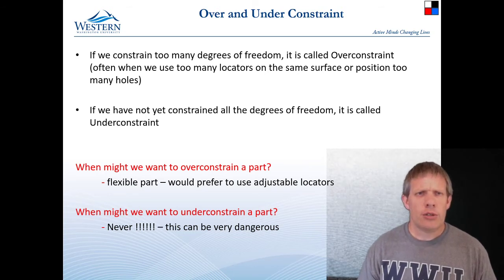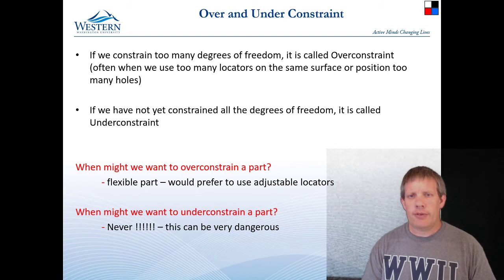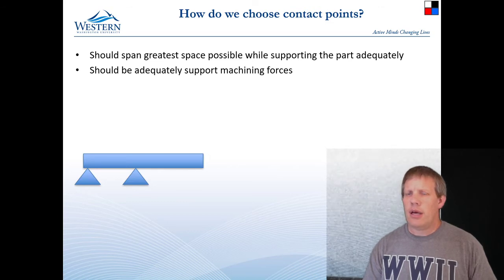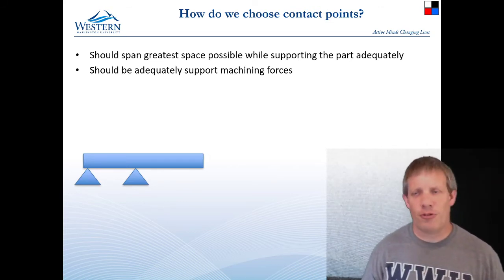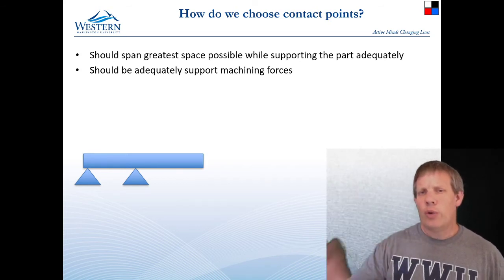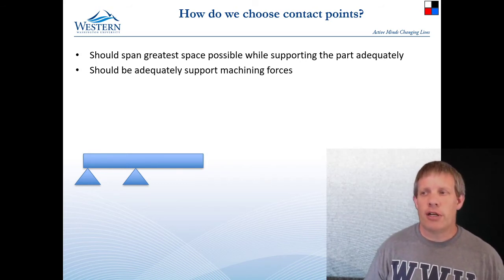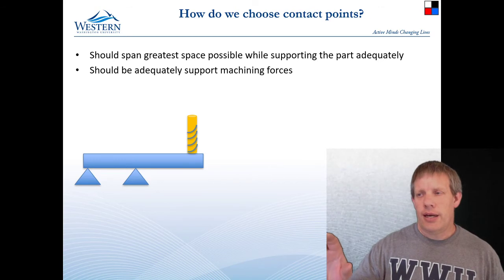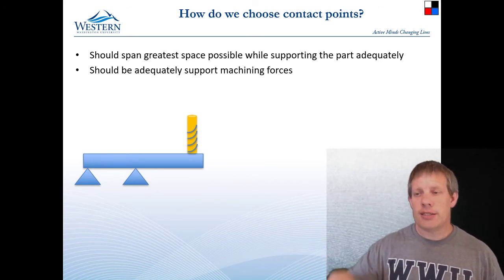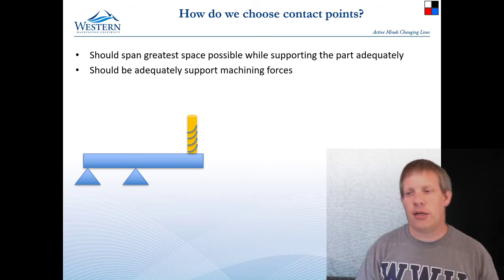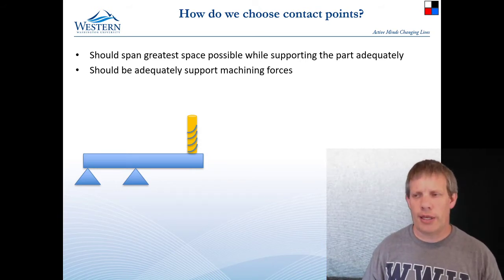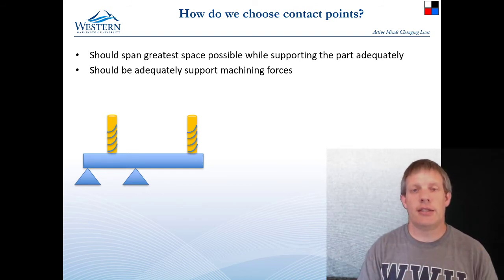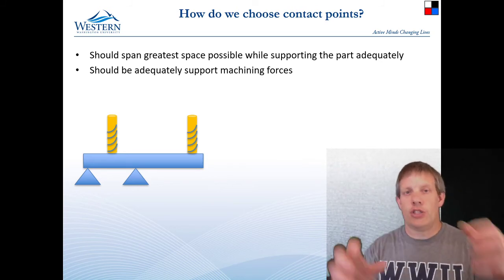All right, so we will, in the next video, talk about, well, let's see. Oh, I guess one last thing. Sorry, I said that before, but one last thing is that we want the contact points to be far enough apart, because we don't want to have a situation like this where the cutting tool is causing a moment that is going to lift the part off of the locators if we can help it. And so we would rather have it so that the force of the cutting tool is interior, inside the locators, so that there is not this overturning moment.